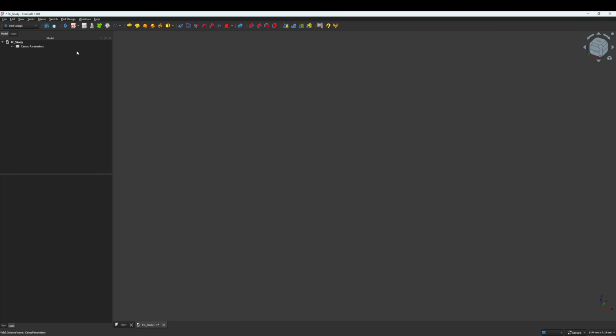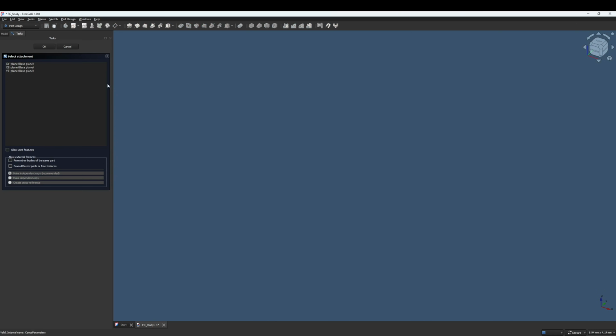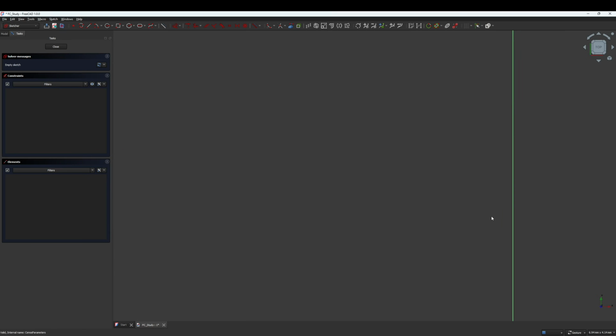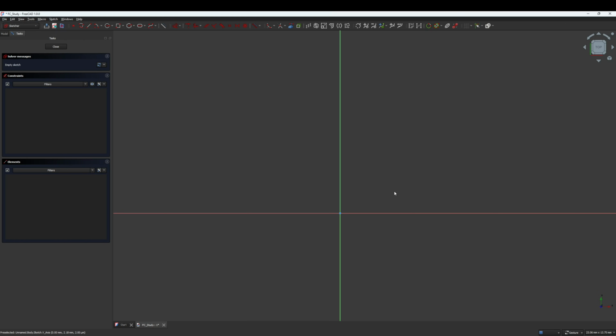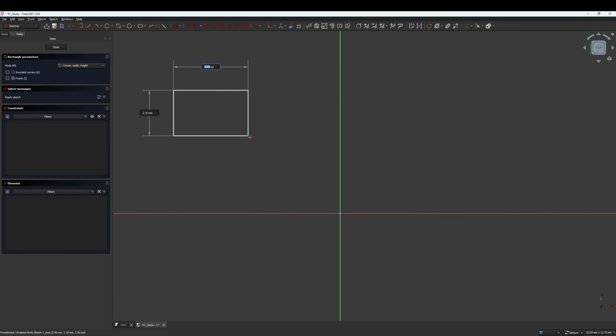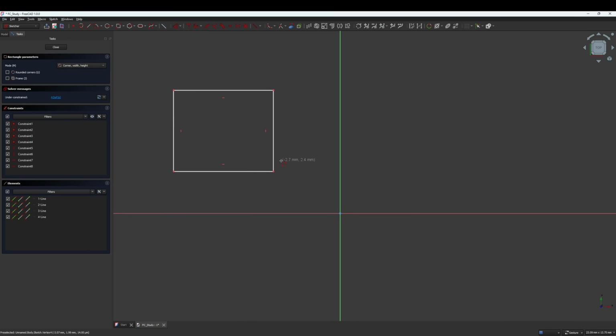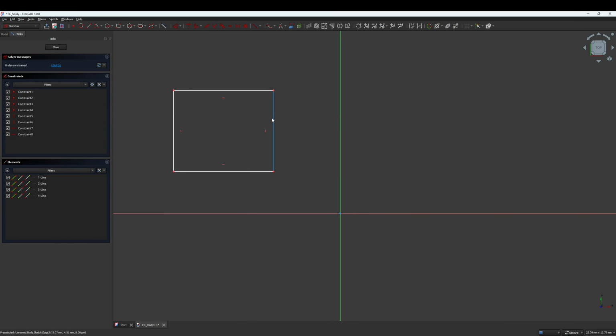By default, FreeCAD opens in the Part Design workbench. You can easily click Create New Sketch, choose the sketch orientation, and click OK. Now you can begin drawing. The upper toolbar offers various drawing tools and constraints to define line quality, the dimensions, and more. You can also dynamically draw and reposition your sketch.